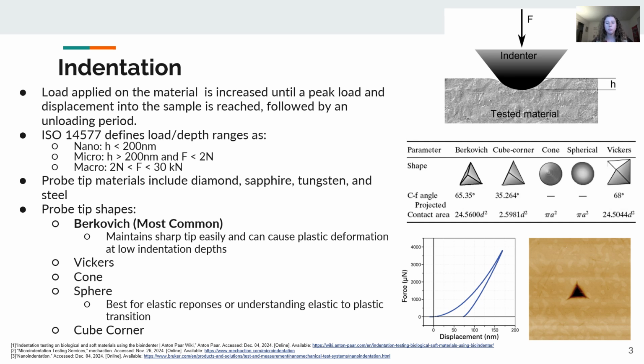The Berkovich tip, which is a three-sided pyramid, as seen here, is the most common because it can keep a really sharp tip easily and be manufactured easily, and it can also cause plastic deformation at low indentation depths, making it an ideal choice for thin film analysis.